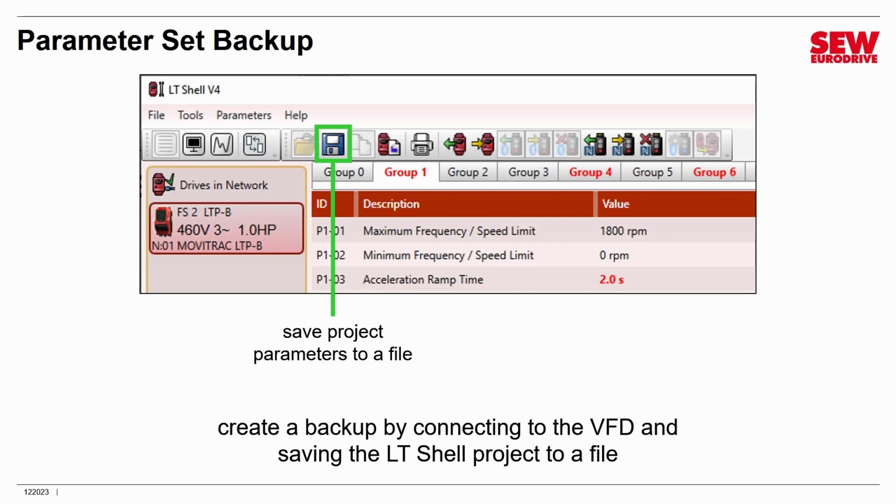This has nothing to do with backups, but I'm going to point it out right here. This is a good time to talk about it. What if you want to factory reset your VFD from within LT Shell? Can you do that? And the answer is absolutely. You don't have to hold down that keypad button combination. You can simply click this button right here, and that will wipe your VFD and set it back to the factory defaults. So that's just handy to know. You can reset your VFD from right here.